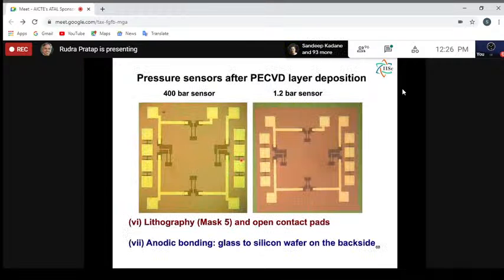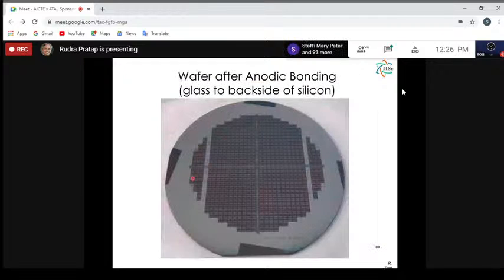And after fabrication, they look like this. Whenever pressure is coming from normal to the surface, okay, so pressure is applied, the membrane deflects, and once it deflects, there is strain here, right? And this is the strain in the piezoresistor that unbalances your Wheatstone bridge, and by balancing it, you can figure out what is the strain there, and from there you can back calculate to know what the applied pressure is.